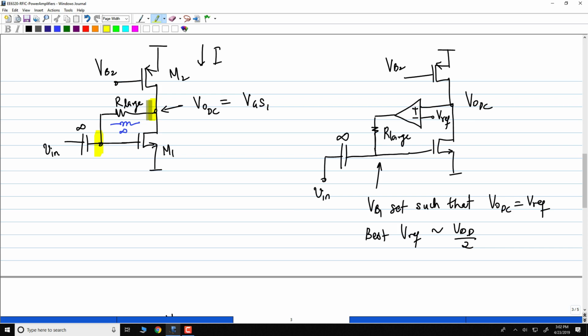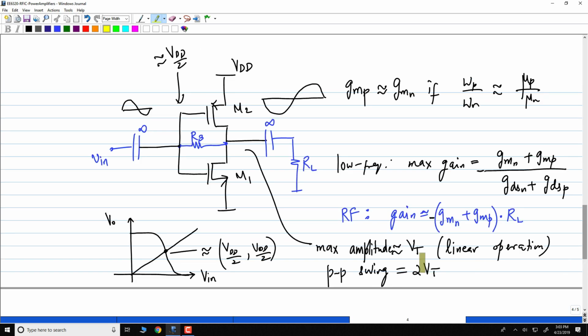Okay. So actually, I was remembering the phasor diagram which I used to draw in class one. There the voltage-current relationship, resistors usually don't really shift the phase. Correct, because there's only a real part of the impedance. So the current through the resistor will be in phase with the voltage across the resistor. That's all you can say about the resistor.